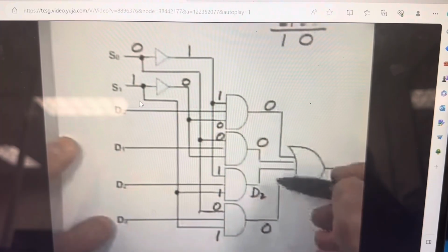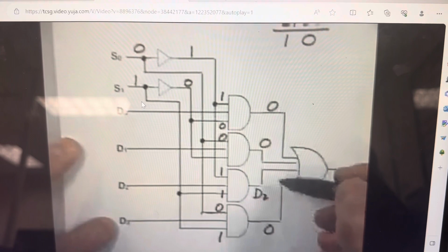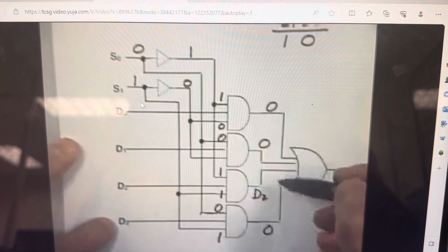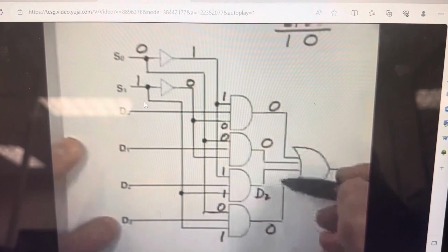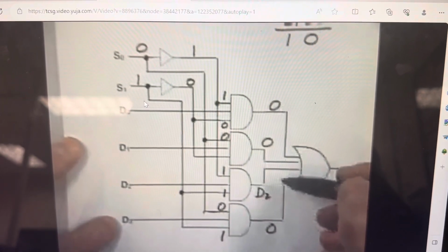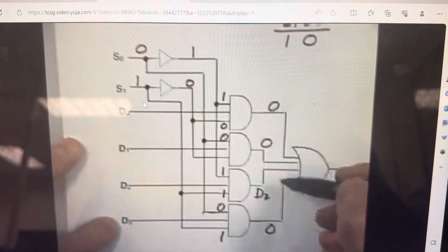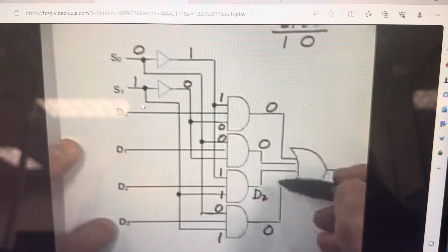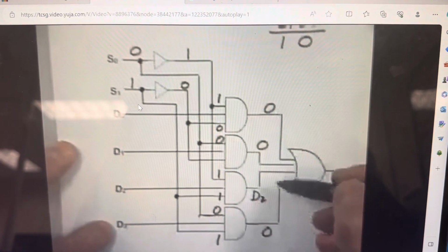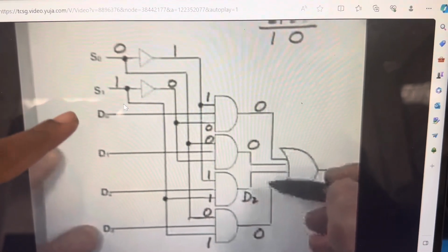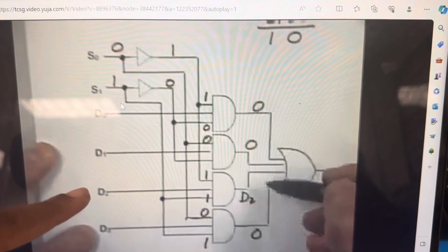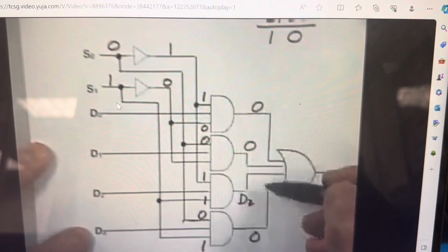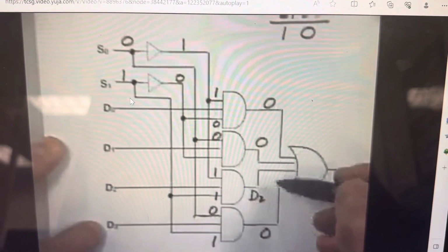The multiplexer works as the following. The input put into the chip will correlate to a number put into binary. Here we have 2 as 1, 0 as the input. And that will correlate to one of the other inputs labeled 1 through 4 here, but depending on the chip, it could be 1 through 8.